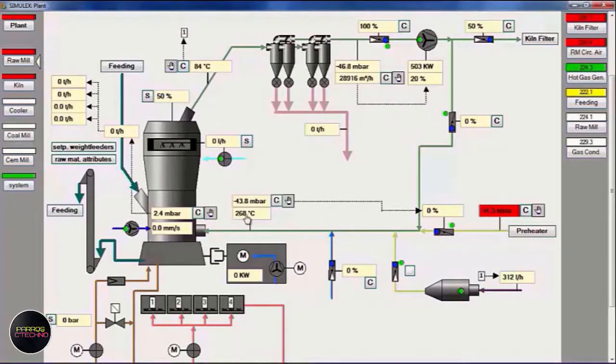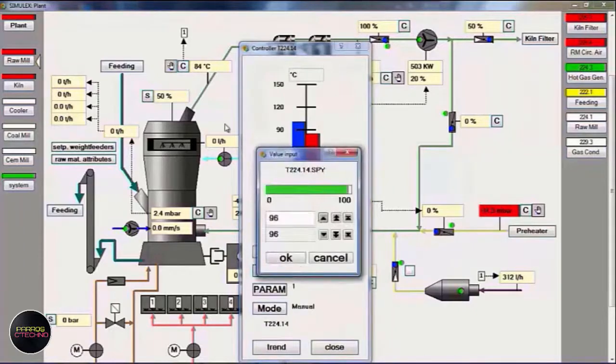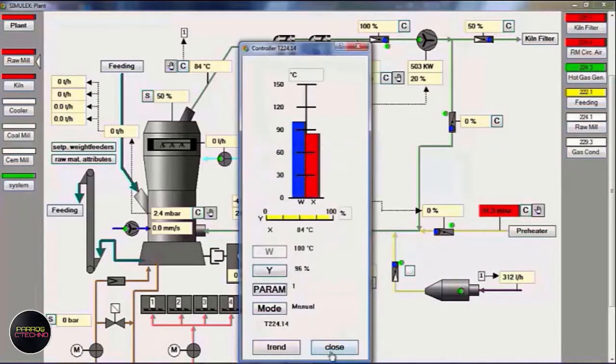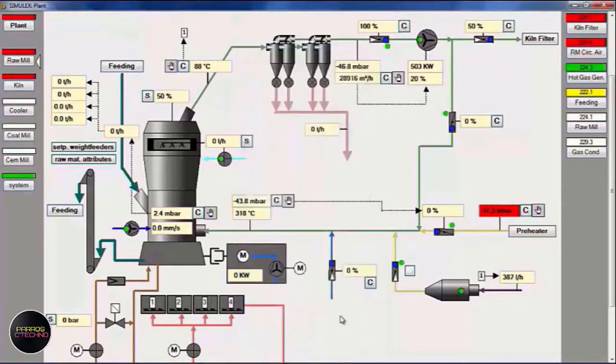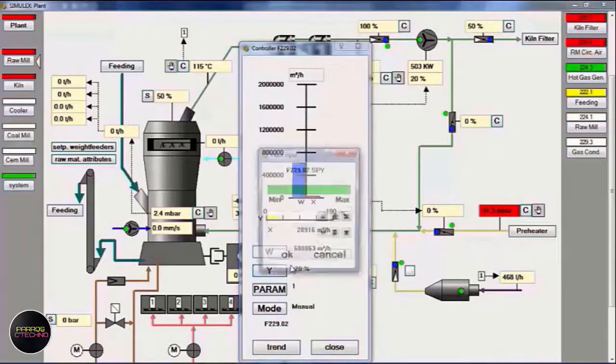After this, we see the temperature at the inlet mill goes down and the outlet mill goes up, so we try to add more fuel and increase it. We'll try the earlier calculation, it's about 93% for feeding 50 tons per hour. The temperature at the outlet quickly rises above 100 degrees, and at the inlet mill it was over 300 degrees Celsius. We increased the damper opening again.